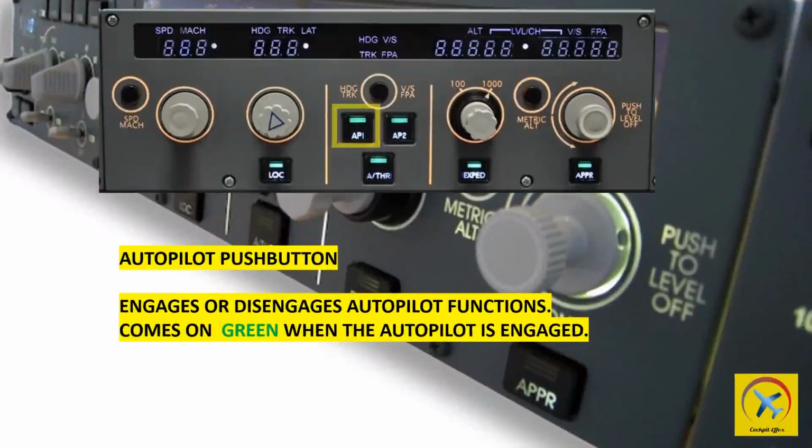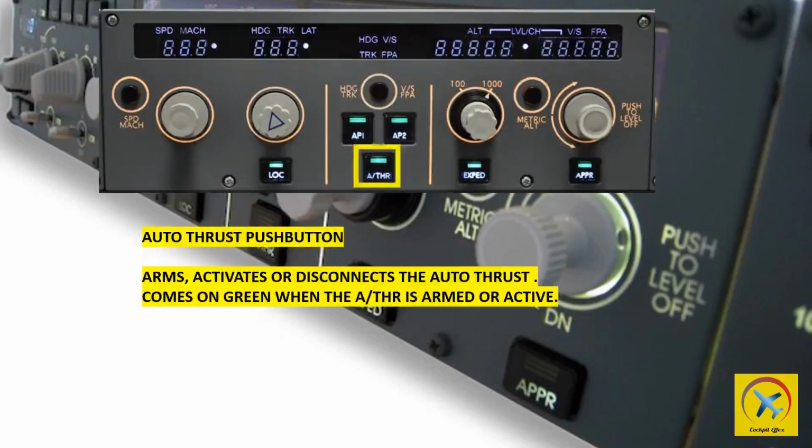The autopilot buttons engage or disengage selected autopilot. Autopilot guidance modes are selected on the FCU and MCDU. Engagement is confirmed by the flight mode enunciation on the PFD. The autopilots utilize ailerons, rudder, spoilers, and elevators to achieve the desired flight profile. Rudder inputs, yaw damping, and rudder trim are computed by the FACS and are automatic when an autopilot is engaged. The autopilot also provides inputs to the nose wheel steering unit during the rollout mode on an auto-land approach.